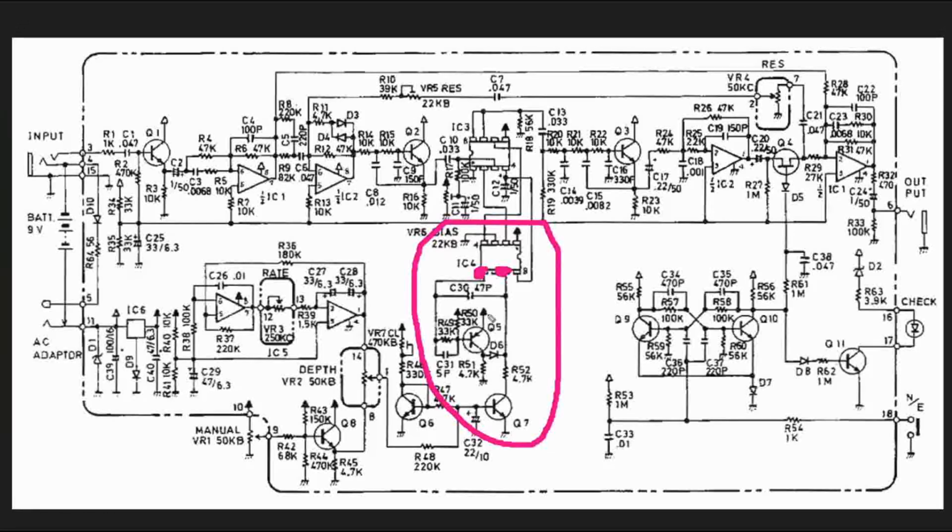And this transistor has one side connected to power, the other side connected to ground, and a polarity diode. So that what happens is that this oscillator is governed by the value of this capacitor and also by how it's charged and discharged by way of the resistance that is seen